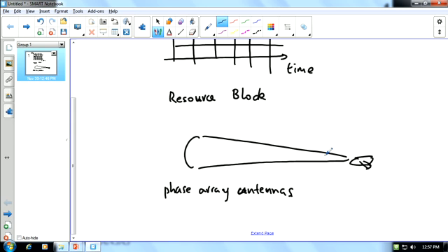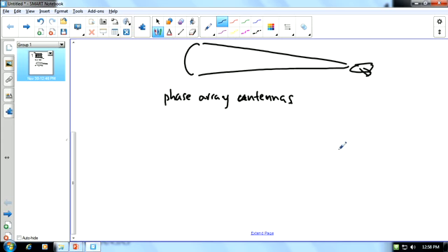By using phased array antennas, we can do that, and the same theory can be used for communication. We have multiple antennas, and we can steer the beam of the antennas to different locations. And if we have many antennas, we can create multiple beams simultaneously. Okay, and each beam will serve a single user, and in this case, there is minimum interference among the users. That's one of the enabling technologies for the 5G communication systems, okay? It's called multi-user MIMO. MIMO means multiple input, multiple output.